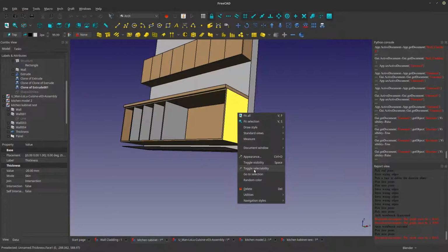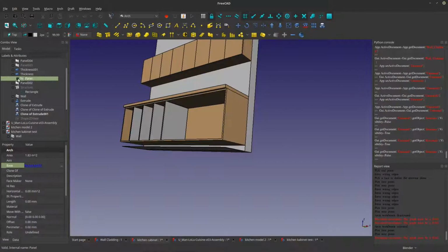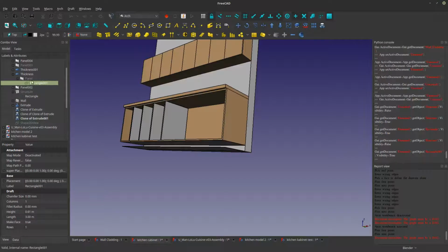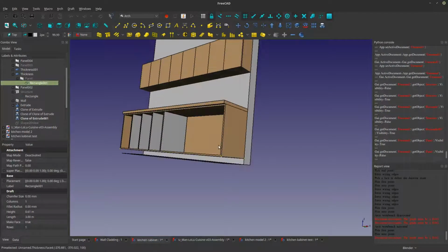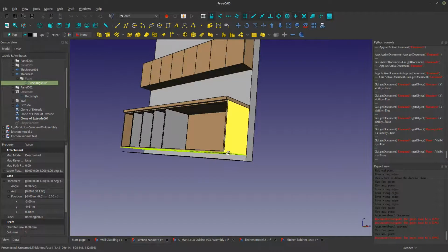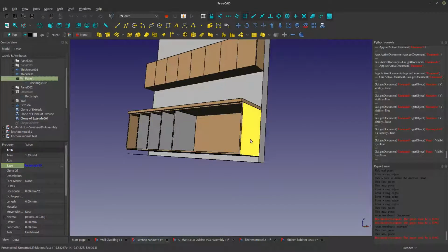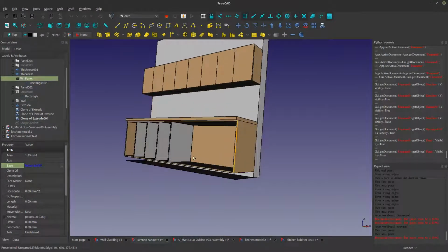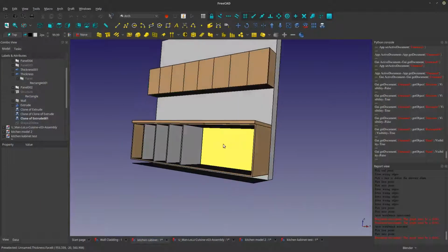Go to selection. It's a rectangle as well that you see here. I just moved its placement position to 0.1 meter above the initial one, and so I created a panel about this height, and then I created a thickness inside which gives me the hole.